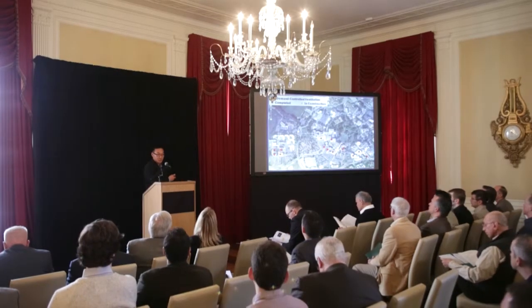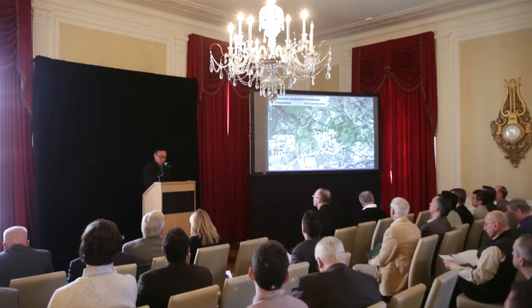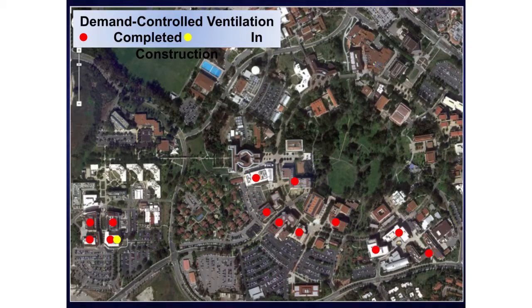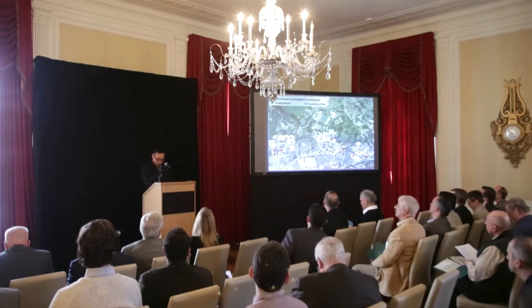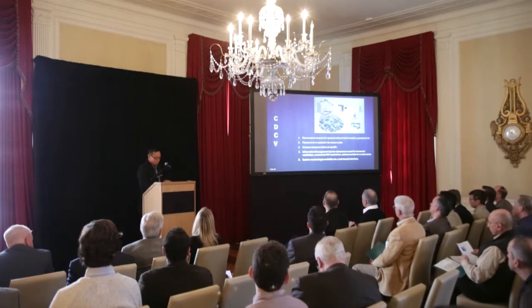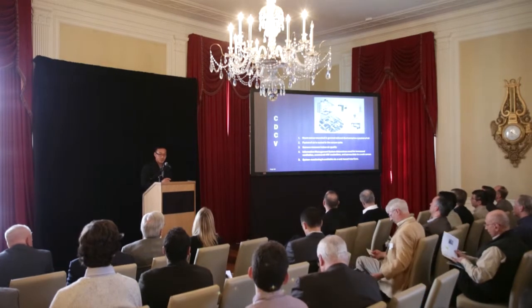So we currently use CDCV, centralized controlled demand ventilation, to manage air changes on campus. We have it installed in 13 buildings with several in construction. All but one are retrofit projects. So let's just take a look at how CDCV works.